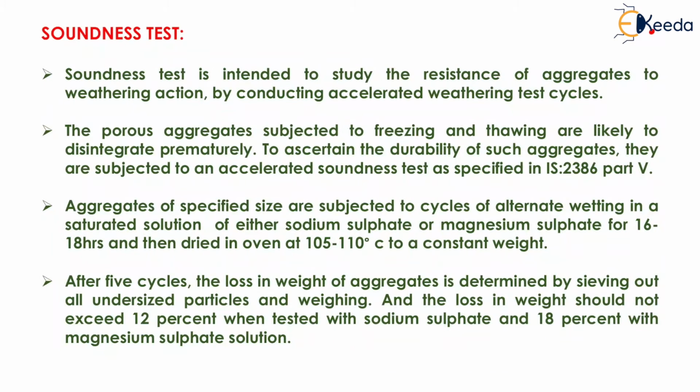Now, the next test is the soundness test. Soundness test is intended to study the resistance of aggregate to weathering action by conducting accelerated weathering test cycles. The porous aggregates subjected to freezing and thawing are likely to disintegrate prematurely. To ascertain the durability of such aggregates, they are subjected to an accelerated soundness test as specified in IS 2386